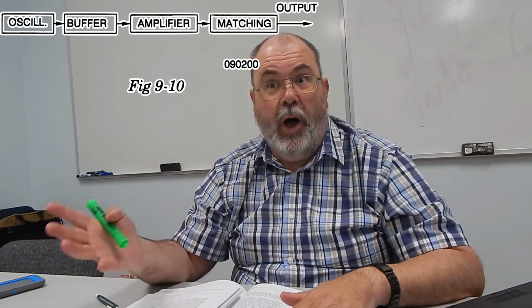How much power do we want? But we amplify it. The amplifier may be one single tube. It may be a series of transistors. It may be dozens of devices, but it's just a block. We're going to amplify it. We need to match that typically to our 50 ohm antennas. If you throw up a wire in the air, it may not be 50 ohms. It may be some weird thing like 300 ohms.